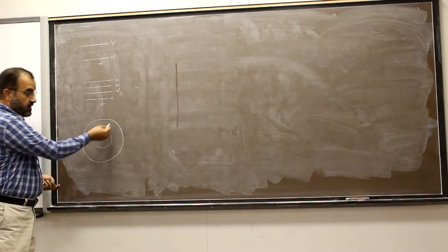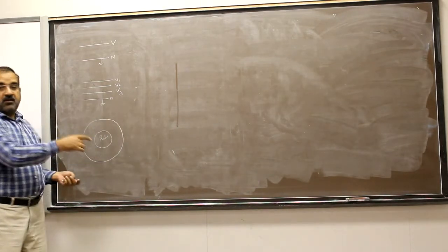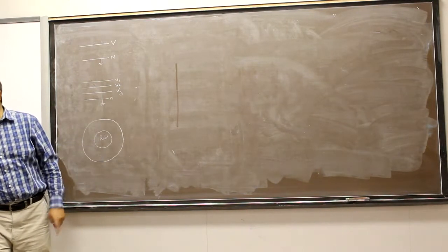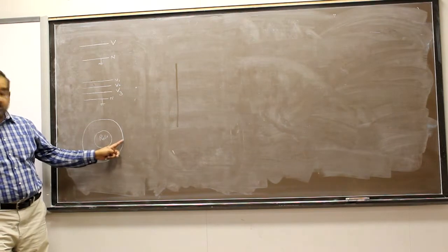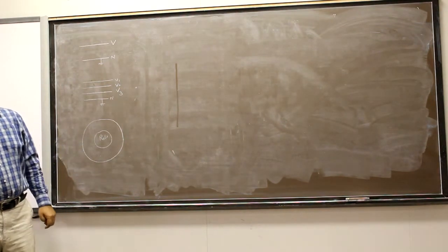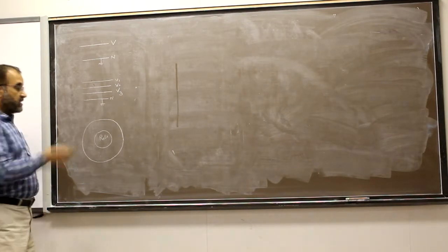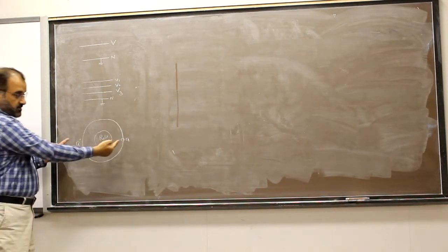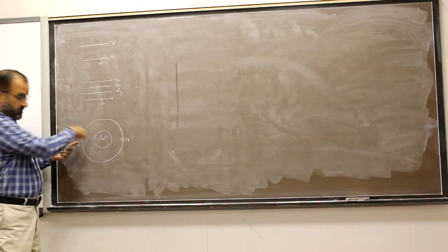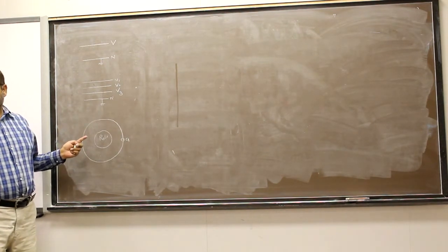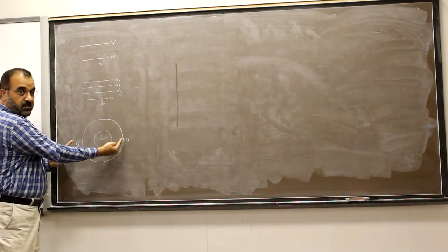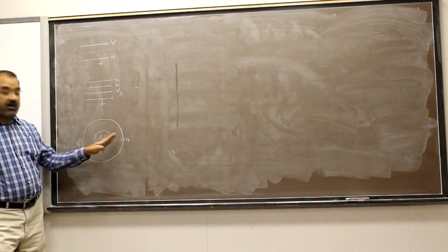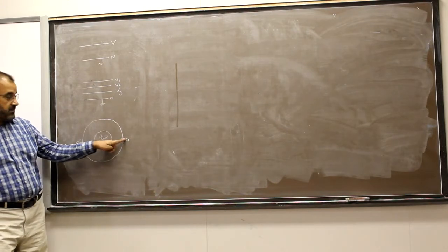Now what we do, we have to divide this from zero angle up to here, a total 360 degree circle. When I divide this 360 degrees into three equal parts, it will be equal to 120 degrees. So if I say this conductor is A and this is A dash, we put the conductor winding from here and take it from the other end, one conductor, one winding, one coil. So this will be one. With respect to this one, I will put another winding which should start at 120 degrees from this angle.